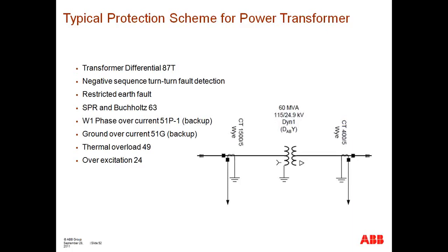One question is, does the sudden pressure relay really operate on rate of change of pressure rather than just change in pressure? Yes, it's a rate of change of pressure. So it's a rapid change of pressure that will in turn trigger the SPR. That is correct. There are some schemes, but it's one of those gray areas.